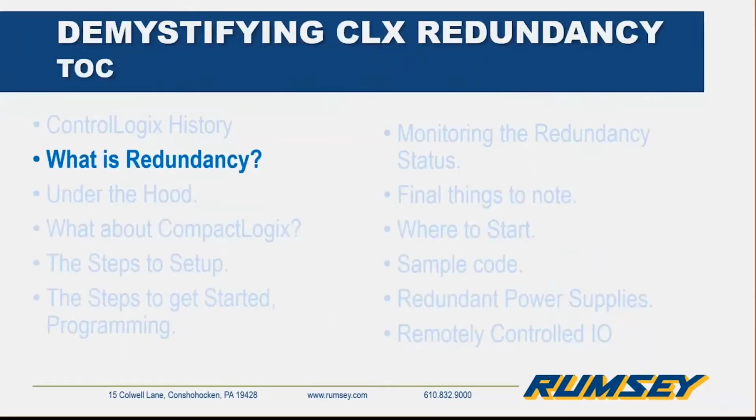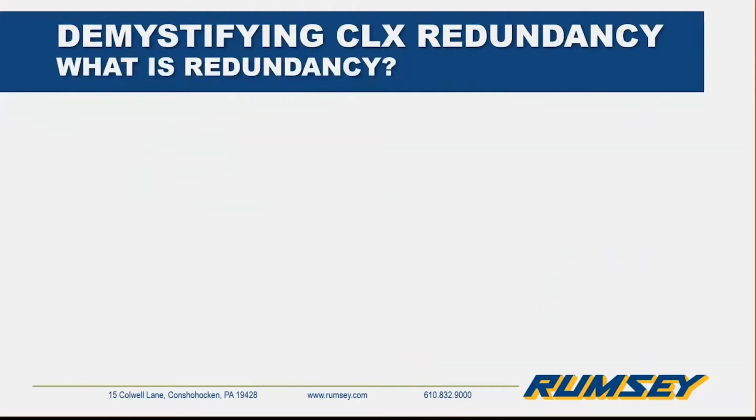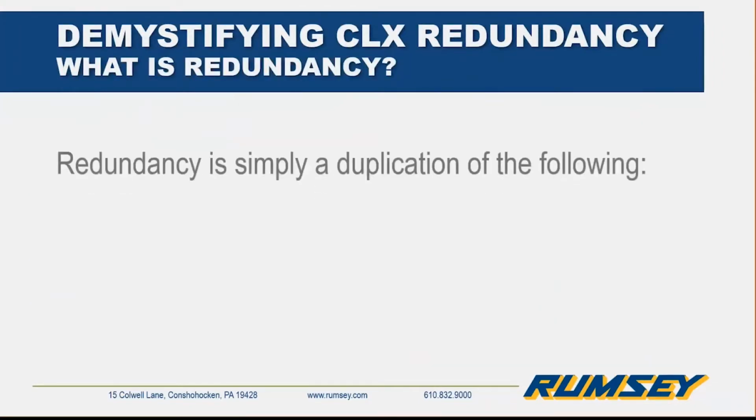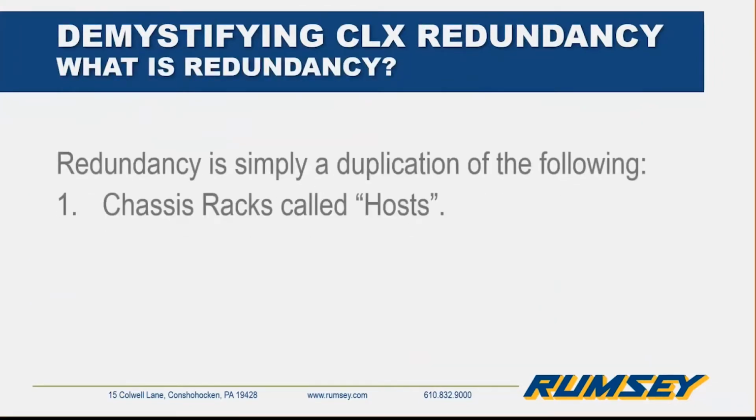All right, so what is redundancy? In short, it's a duplication of the ControlLogix racks. They're nicknamed hosts. Some documentation shows it, and when you're talking to Rockwell or other people, they usually call them hosts. But the bottom line is that would be the pair of processors that are for your control system. Then you're going to have two PLCs